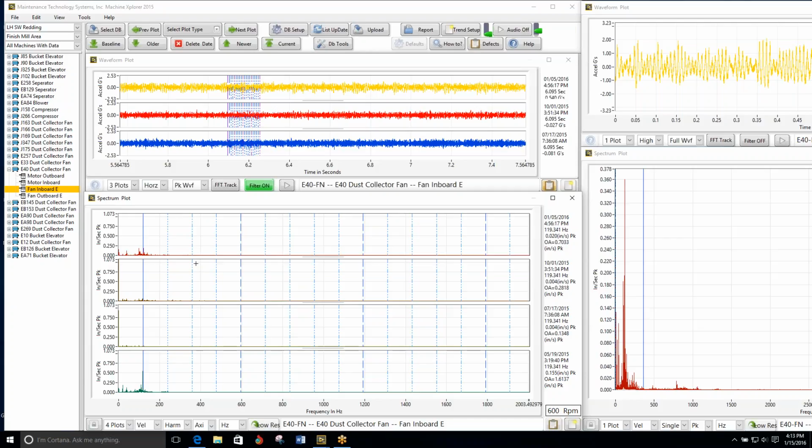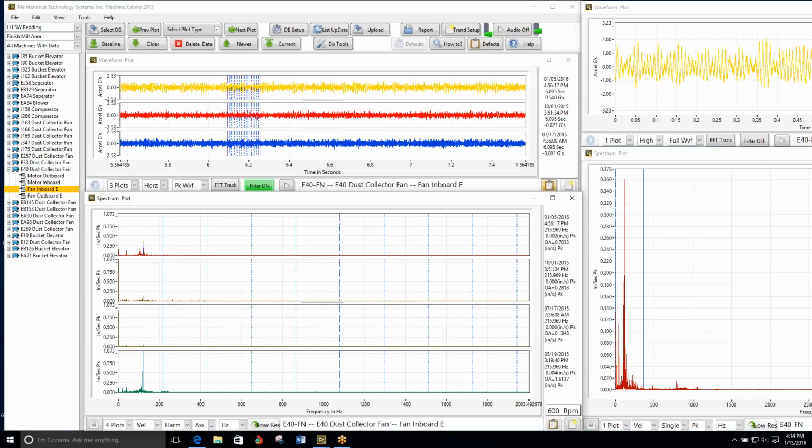That's about 120 hertz, it looks like. Let's see how close to 120 it really is. Just under 120. So that's pretty close to 120, so that very well could be electrical. Yeah, but that's in the fan bearing, not the motor. It is on the fan bearing. Yeah, good point. Well, that looks to me like it's going back to where it was when they repaired it.